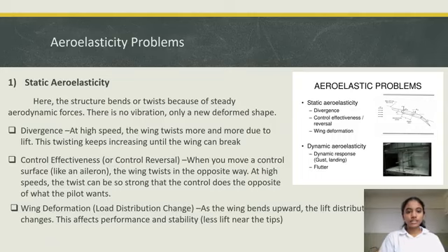We will see the aeroelasticity problems. First is static aeroelasticity problems, and second is dynamic aeroelasticity problems. Here, in static aeroelasticity, the structure bends or twists because of steady aerodynamic forces. Basically there are steady aerodynamic forces, no vibrations are included, and no deformation of the shapes.